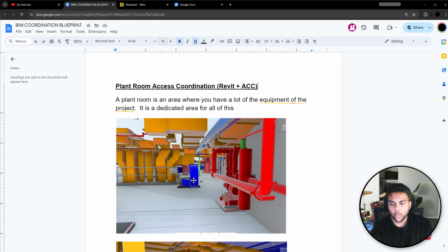So what we had to do was say, okay, we can put it on the floor. You might be thinking, we can't put it on the floor because it's below 2100. Like you told me the rule was that it has to be above 2100. The reason you can put it on the floor is because there's no hazard of you hitting your head here, because you don't walk under it. So you have to think, when can I walk underneath something and when can I hit my head? You might be thinking, this pipe, can't you hit your head? No, because there's no need to go over here.